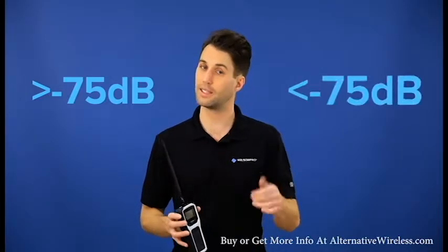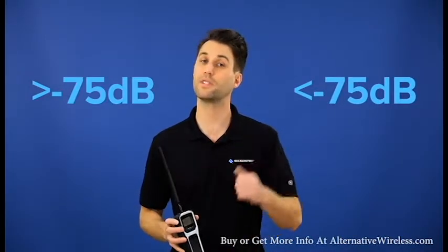Once you have all the data logged, now you have a good understanding of the cell signal level at the job site. If the majority of your readings are better than -75 dB, then you've got a good strong signal to work with. If most of your readings are less than -75 dB, then you'll want to visit the FCC Spectrum Dashboard website.